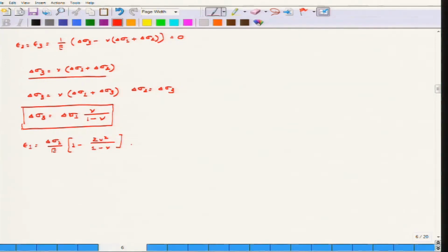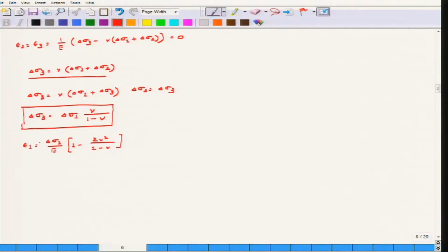Now, remember we are deriving all this from the basic definitions of solid mechanics, considering compression as positive, because in case of soil, we will always take compression as positive. That is why I have ignored a minus sign here. If you really want to see how you can derive this from the basic definitions of solid mechanics, you will always see that there is a negative sign in front of this, where you take compression as negative. But these are all from the definitions of solid mechanics, whereas we take the sign convention of soil mechanics. That is why epsilon 1 is always said to be positive.